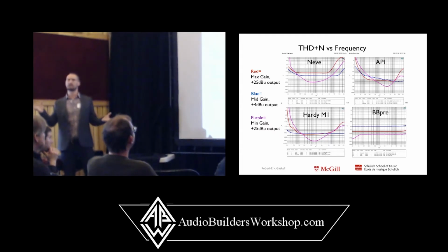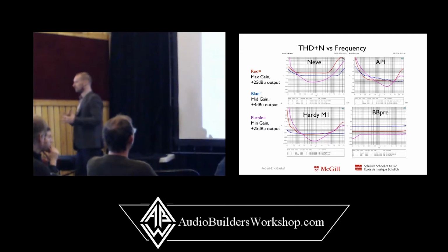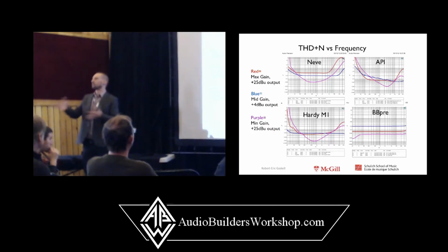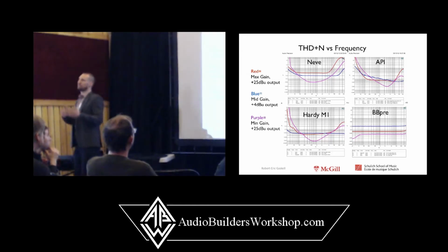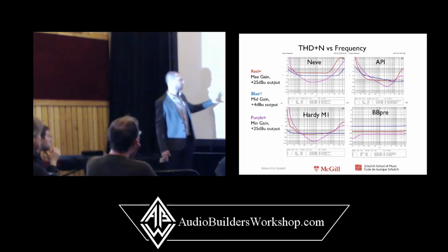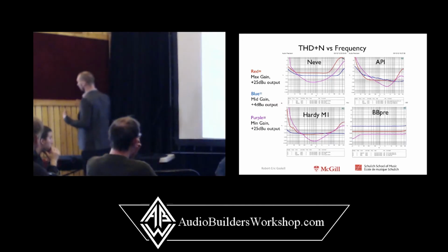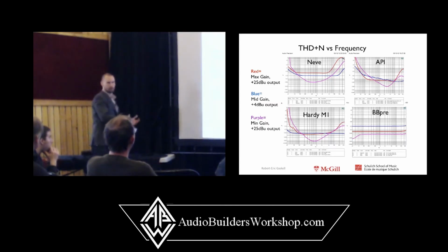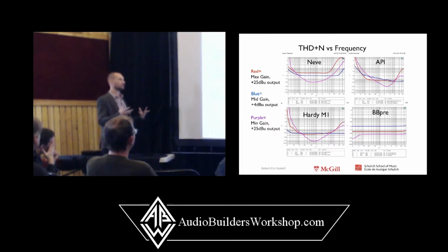I will mention there's a certain type of plug-in, virtual bass synthesizers, virtual bass systems that intentionally add low frequency distortion to your signal in order to give you a sense of virtual fundamental. The idea of these things being that if you're playing back music over a small system that doesn't have bass extension, if you have the harmonics of the fundamental, your brain fills in the existence of the actual fundamental.